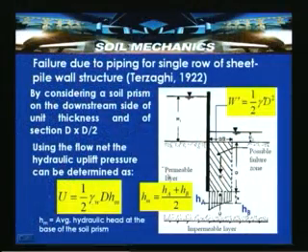Once the Hm is known, at the base of the prism, what is the uplift pressure exerted by the pore water pressure existing at that point? As the flow takes place from the upstream side, there is a dissipation of pore water pressure, but whatever is existing at points A and B, based on that we calculate the total heads, and then that is used in calculating the hydrostatic uplift pressure.